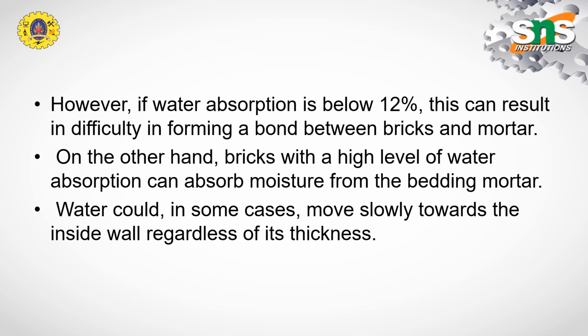we will find difficulty in bonding the bricks and mortar. The binding property will be lost if the absorption of the brick is below 12 percent. The brick has to absorb a certain percentage of water, then only the bond between brick and mortar will be good.